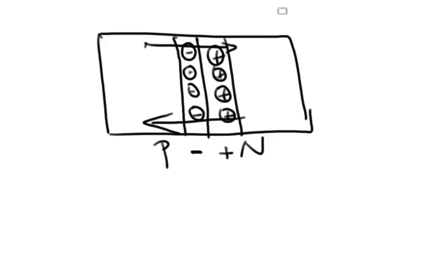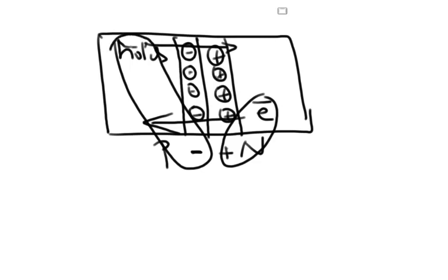And if you compare, the diffusion process was holes moving from this side to this side, while electrons were moving from here. Now if you look at these symbols, they both are opposite fields. Now this field pushes the holes and electrons to return back to their respective positions.